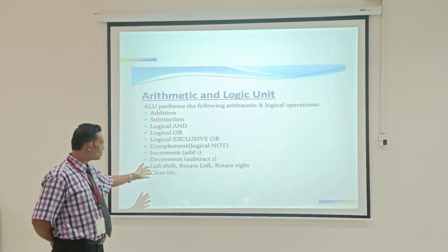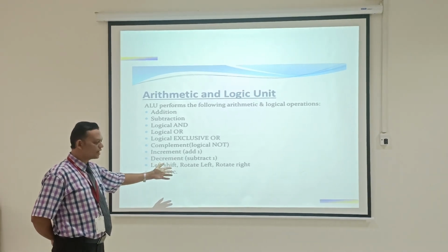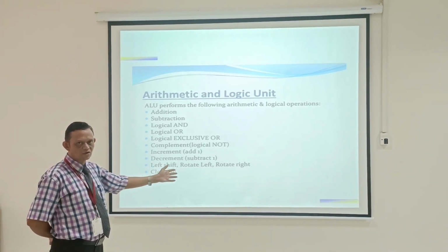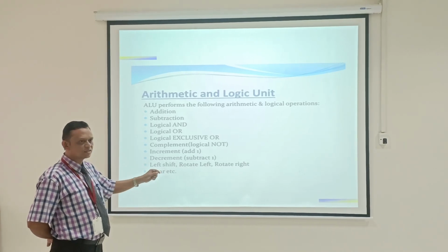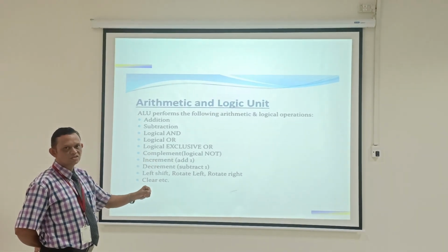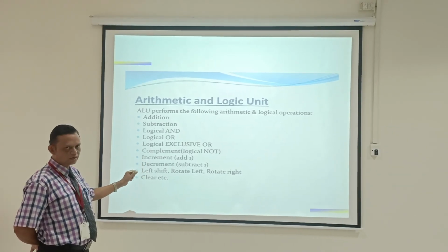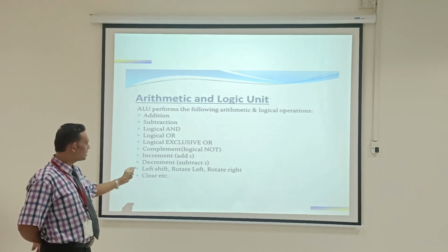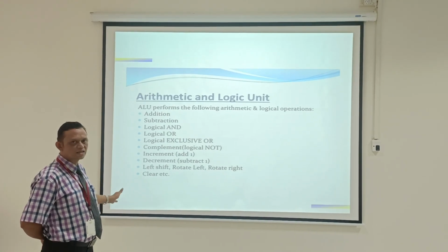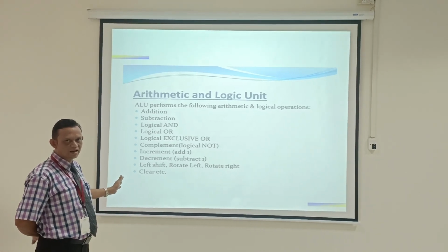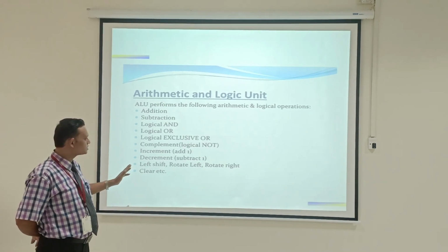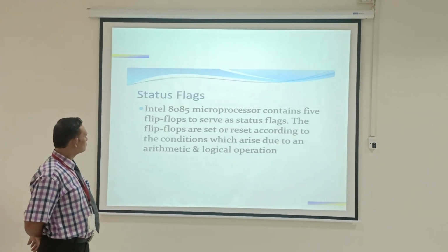And you see that there is rotate left and rotate right. In a shift, the end bit will be left over. But in the case of rotation, the bit that is left over comes back into the first position, so it is called rotate. There is a little bit of difference between the terms shift and rotate. Another one is the clear instruction, which we generally call reset, where everything comes back to the initial stage. That is called the reset or clear function.